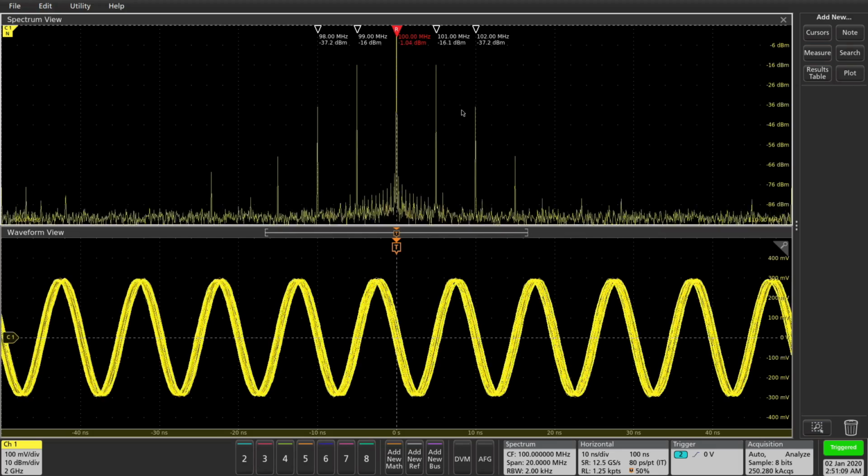Now this is a sinusoidal modulation, which is why we see the nice Bessel functions there, but I can change that from a sinusoid to a different type of modulation. Instead of sinusoid we can do square. So what do you expect to see? Well, you will not see this clear smearing of the zero crossing with high persistence there, because with a rectangular modulation, you will only have two states. So let's go ahead and try that.